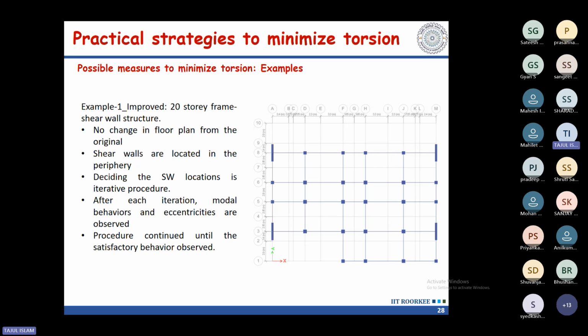Flexural behavior. When you are talking about stiffness and bending moment, it will not depend on your structural element type, whatever you have chosen. If you are relying on that, that is wrong, because load will come from your configuration, not the element type. So if you are relying on the software, using some other element to reduce the moment and reduce the stiffness, or increase the moment or stiffness, that is not a good thing to do. But it will give improvement. You have seen that by creating the spandrel, the torsional resistance is improved.